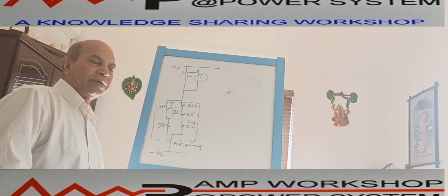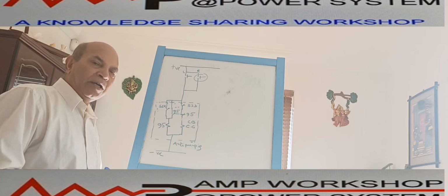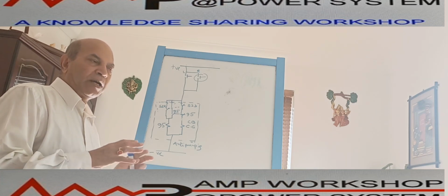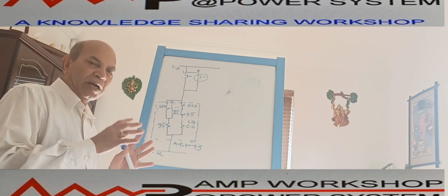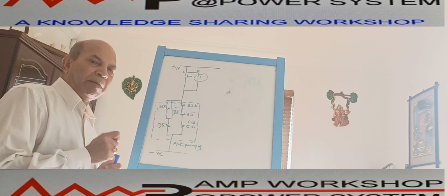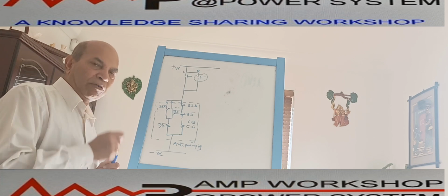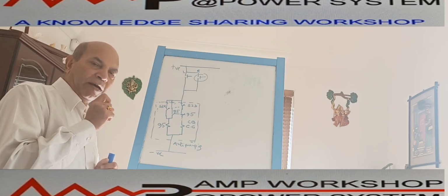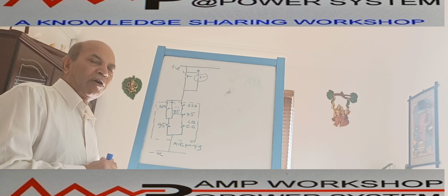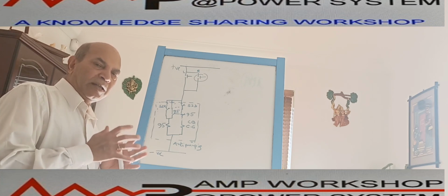There is one feature in the circuit breaker which is inbuilt inside the circuit breaker enclosure. You cannot get access to that. You know, when the making and breaking is taking place, it is inside a closed chamber. Inside that is this anti-pumping device, which prevents the continuous maintaining of the closing command. This is done through a circuit called the anti-pumping circuit, which is inbuilt with the breaker itself, inside the breaker chamber.